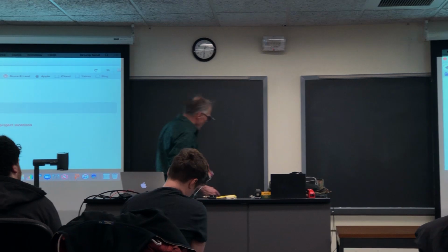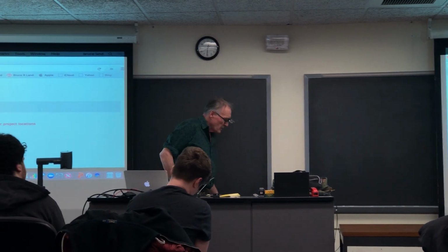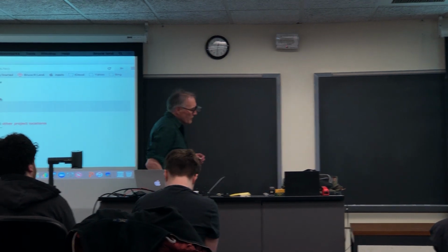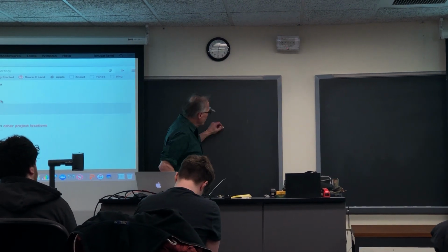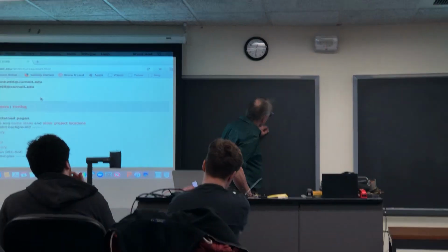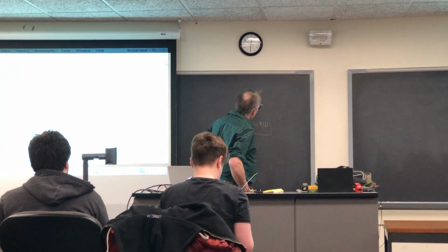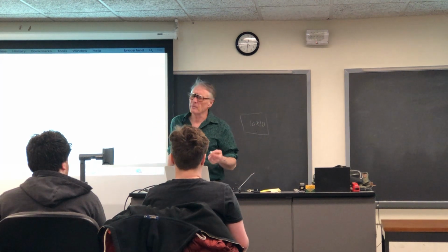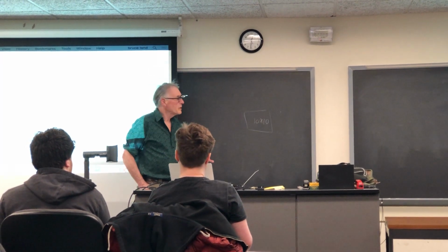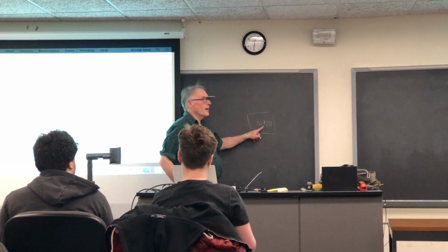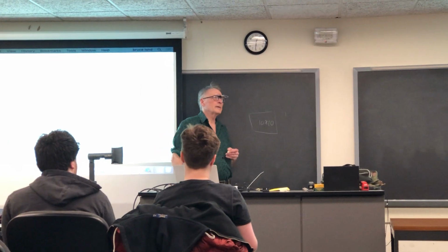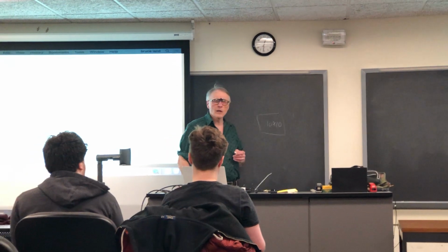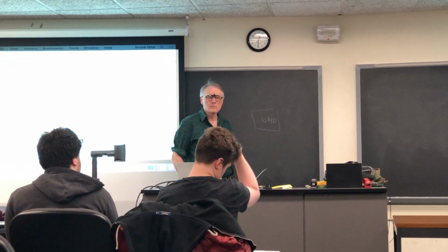In terms of the drum, I suppose if you have different regions of the drum, you could map each one. Let's say you're going to have a 10 by 10 patch of drum, that's 100 nodes. There are 2 state variables per node, probably 3 state variables per node. You need about 1 M10K block to do that.